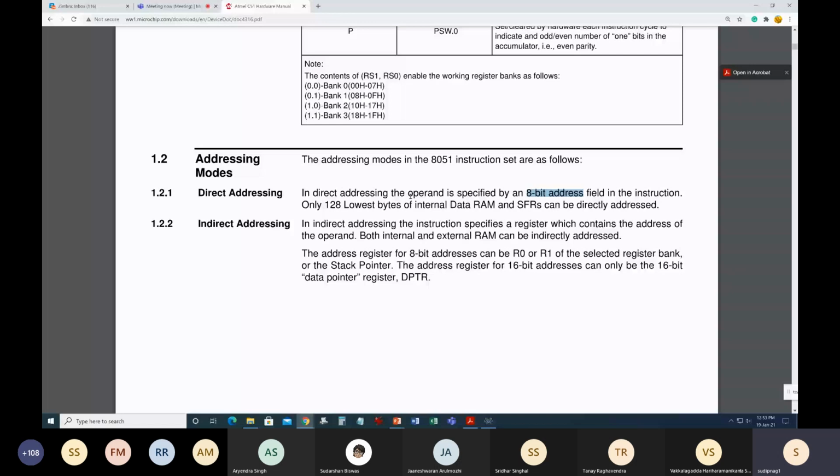But there could be an operand of the instruction, which is basically the data or address given after that mnemonic. So the operand could be either an address or data. Two types of operands are possible, and an operand only comes with a mnemonic, but a mnemonic can come alone. There are instructions where there is no operand, only the mnemonic. The mnemonic is compulsory for any instruction, but the operand is like an assistant to the mnemonic. This operand may carry some address value or some data value.